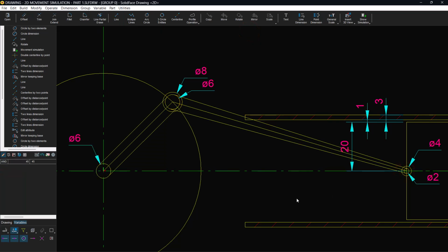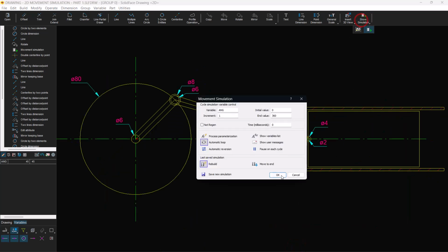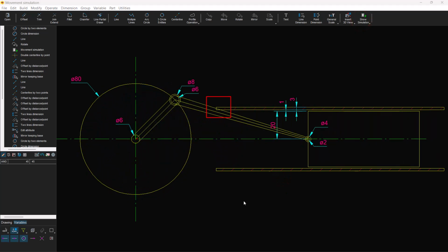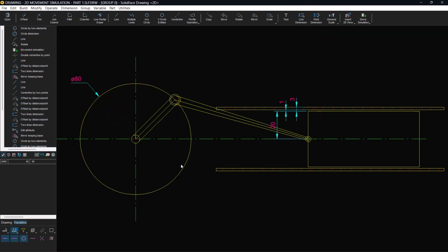At the hand crank line, create two straight lines offset. We could also use two tangent lines, but because of the characteristic of this movement, it can result in positioning errors. Instead, using offsets, the system can handle the offset position better during the simulation. Note that a collision has occurred between the connecting rod and the piston guide. Edit the piston offset, changing the piston offset to 23.